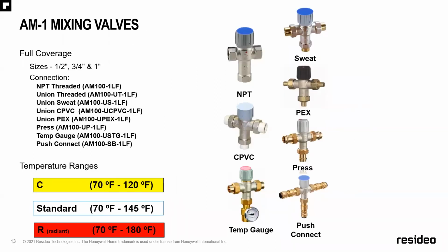So the AMX or the AM1 series mixing valve, this is the tried and true valve. We've had this valve in the marketplace for going on 30 years. It originally started off as the Sparco valve, but now we are the Brockman valve or the Resideo valve. It has a patented Teflon coated thermal actuator. So if you have water conditions that are a little bit more harsh, it will withstand that hardness in the water, and you'll have a lot more longevity.